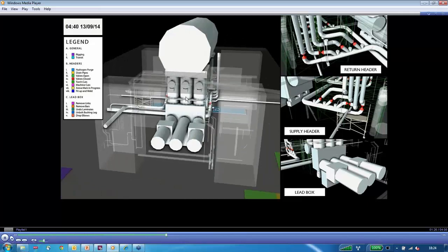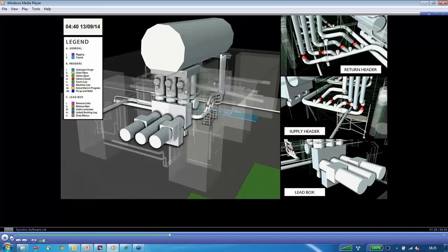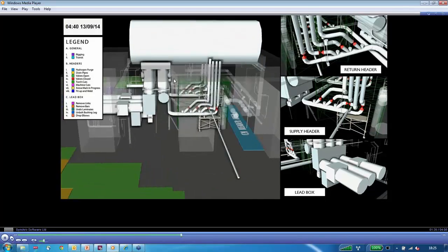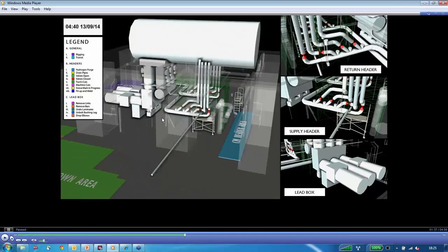For those of you who are into power generation, this is the main side of our lead box. To the right here is the neutral side of the lead box. One of the things we identified early on, I'm hitting pause here in a second on the video, is that we wanted to be done with the 14-inch cuts before the lead box team had to drop the neutral, because that was going to be a space conflict we just couldn't overcome, and one or the other side would have to stop. The other goal was to be done with the 14-inch work until we made an air arc weld at this level. It turned out with the scaffolding and the protection placed, that ended up not being a concern.